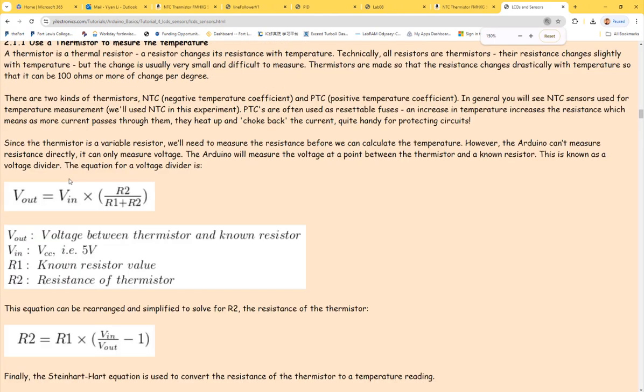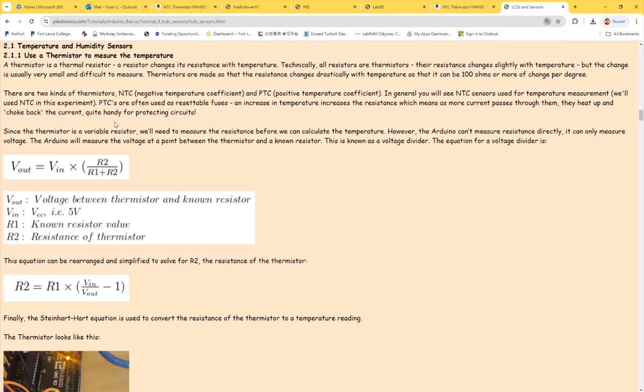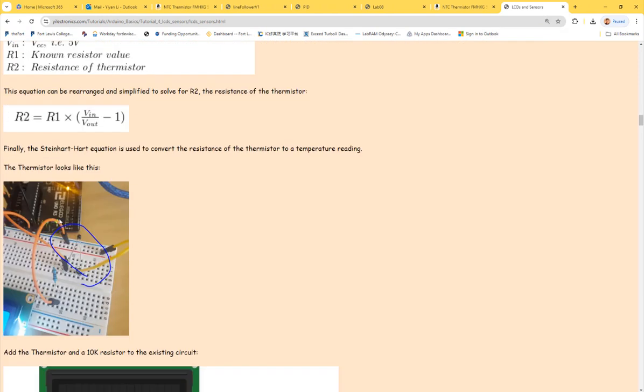Okay, so see here. As a recorder, you can come to this website and look at this. It will be a good contribution to this educational effort, because in the future, if I want to use whatever we have been working on in this class, in my class at Foothill College, I'll probably develop another board. I won't use a Hall effect sensor and something else, but I will definitely include the temperature sensor and display module on it. So if you can figure out a way, for example, you propose what pins you want to use, you look at the GPIOs, you tell me in the proposal, I want to use RA2, RA3, and the ADC AN4 channel to digitize this resistance output.